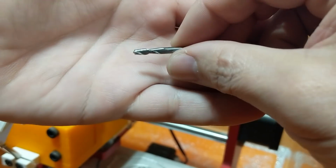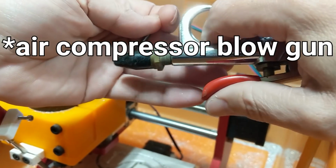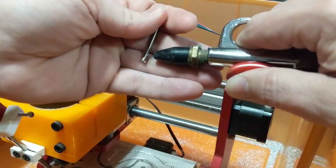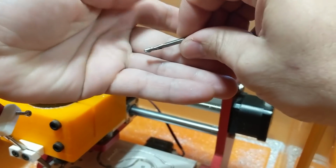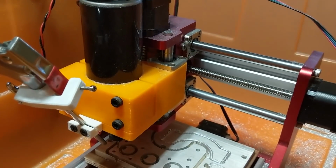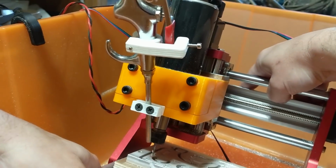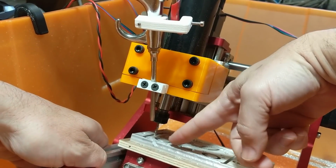And in order to avoid clogging up your flutes with aluminum, you need to clear the shavings more quickly. And in order to do that, I was using just a spray nozzle like this. So I was just following the cut by hand, babysitting the cut and just constantly spraying on it, and that worked. My bits were no longer getting clogged up with aluminum. So in order to not have to do it manually, I've rigged up this other air nozzle from my air compressor. And you can see I've just got some 3D prints holding it in place and keeping a constant stream of air blowing on it.